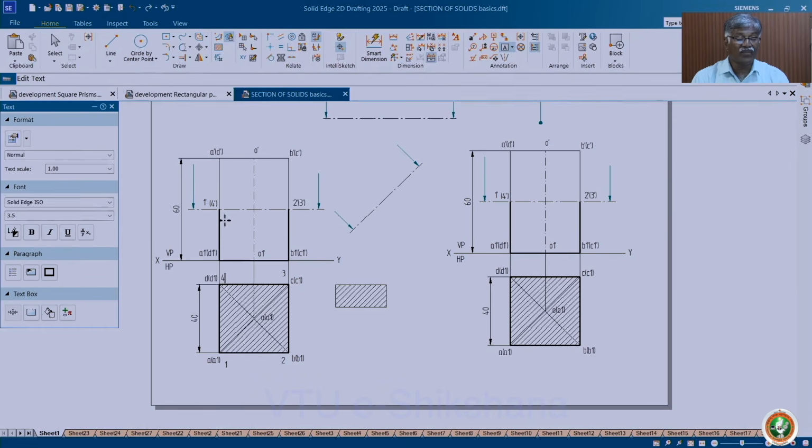Now, along with the section you have the complete area. You cannot see this particular solid, but the remaining portion of the solid is available, and that projection is there. D1 and A1, B1 and C1 are there, A, B, C, D are gone. Now, just retain all these things, you do not remove anything, and you say this is the sectional view along with the section. What is the true shape? This itself is the true shape, because the axis direction itself is perpendicular.